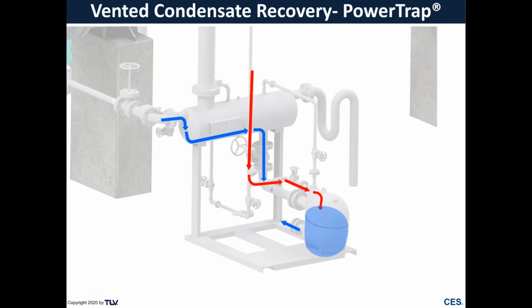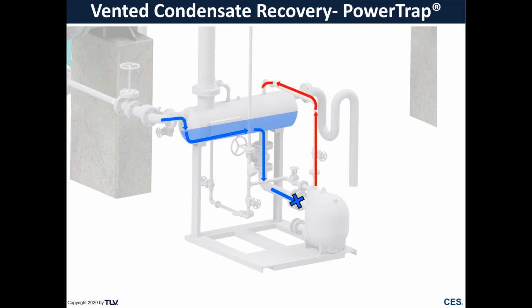During that time, any condensate that comes into our receiver and down to our pump is stopped by an inlet check valve, and condensate begins to back up into our receiver. So this receiver acts as a backup volume. At the end of the discharge cycle, any high pressure motive steam in that body is exhausted back out our balance line into a reservoir, and then condensate again flows into the pump. So this is a cyclic type operation for this type of pump.